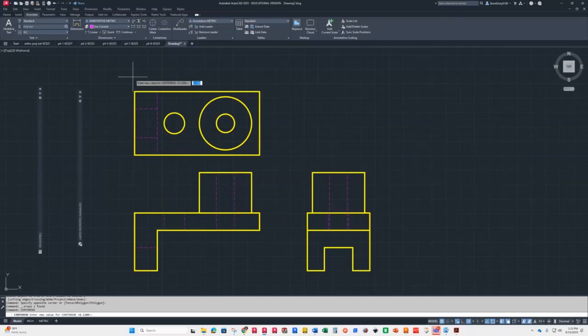The last one you're going to draw that's metric is actually quarter size. So it's 1/4 the size that it really is on the sheet of paper. So then you have to make that bigger. Because you're actually scaling it down, you have to make the stuff that's inside of it bigger, like set the extensions or dimension sizes, that kind of thing. Anyway, this one will work 1-to-1, and I will show you how it works. So do not scale this less than 1-to-1.